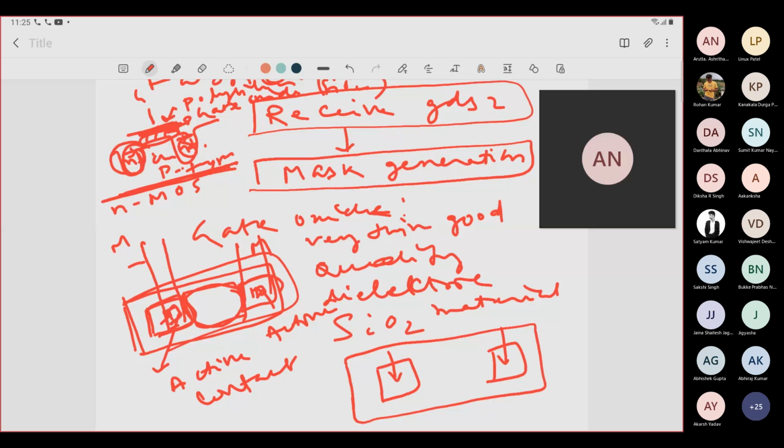When you have a number of devices in a single wafer, you have to first select all the source and drains of a similar type, and deposit the boron material on those selected portions, where you create your source and drain of a particular n type or p type, right?